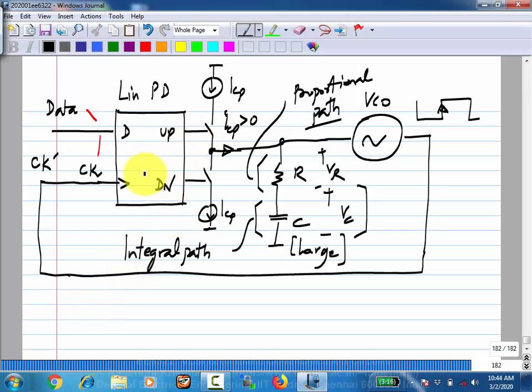And again, I don't show it. I essentially am drawing the clock recovery part, but the same phase detector also gives the data output, right? Because it will have some flip-flop which will have this as the D input, this as the clock input, and the output of that is the recovered data. After the clock phase is recovered, that's what is going to happen. Okay.